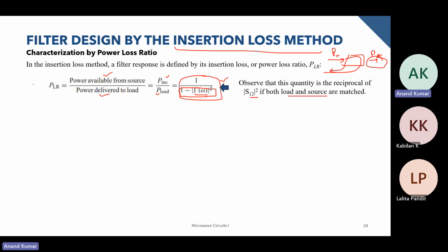Okay, so we have defined the power loss ratio, and this is very important for the designing of your filter. And now we can define the insertion loss as 10 log PLR. This PLR from here, and this is your insertion loss.